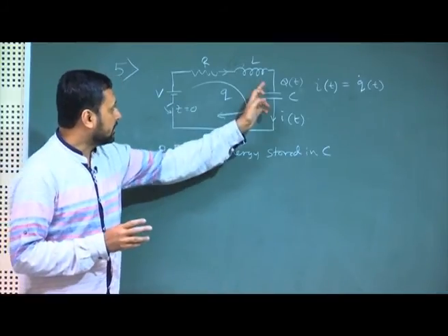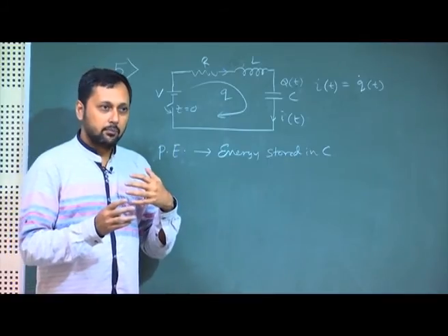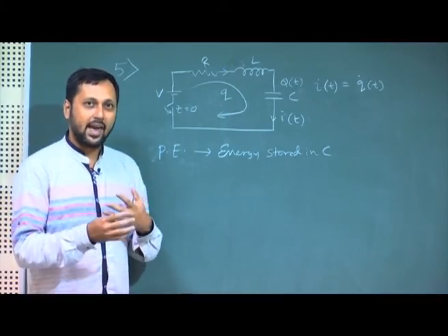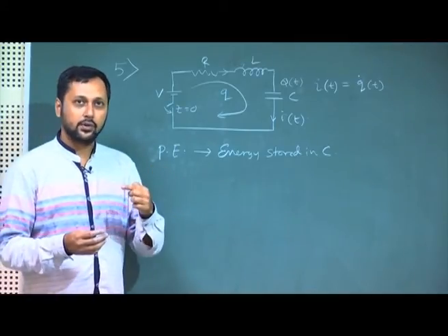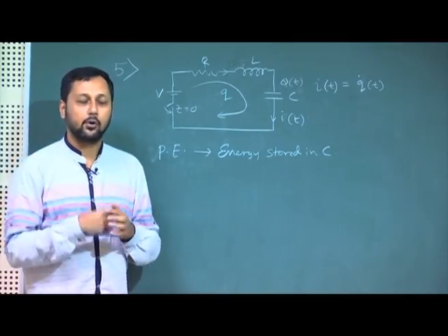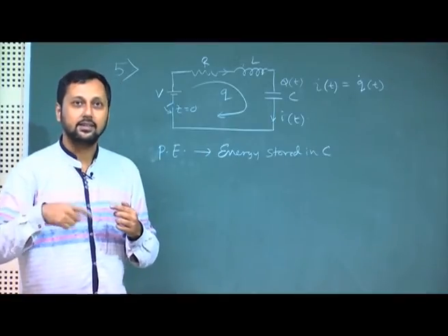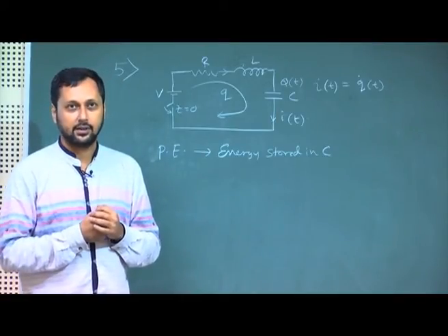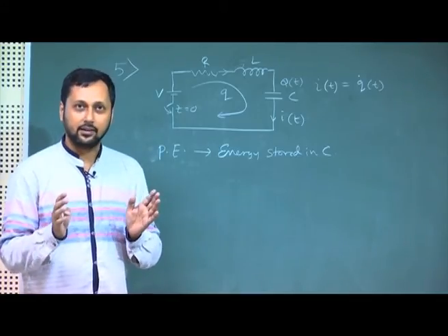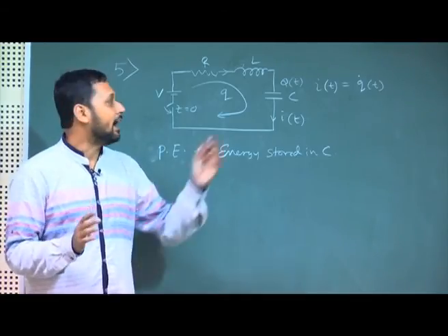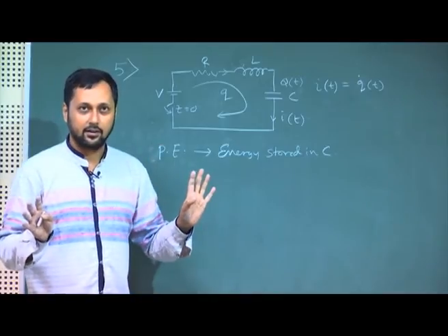An inductor will acquire energy if and only if there is a charge flowing through it which is changing as a function of time, or current flowing through it which is changing as a function of time, right. If there is nothing flowing, nothing will happen. For a DC circuit, a steady state DC circuit, an inductor is nothing.